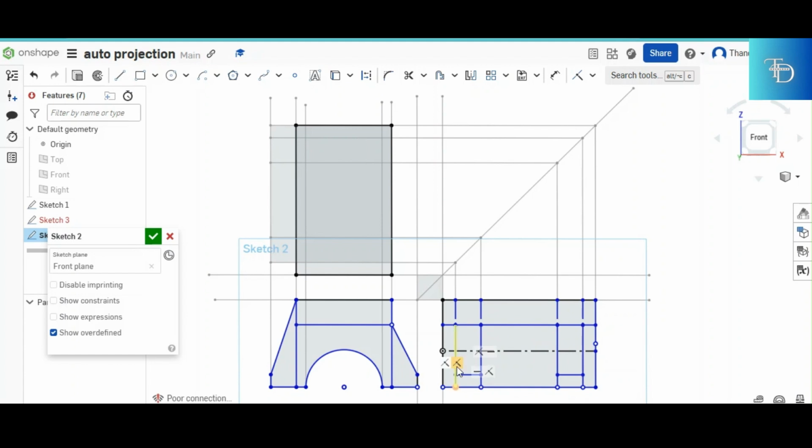Let's start mapping from the side view. The first line is there. It touches the 45, it turns. This right there is the border of your top view. So it starts from there to where? To exactly the vertical. So you make the very same part from the front. When you look at it from the front, and then from the side view, you make the very same part speak the same language using the lines.